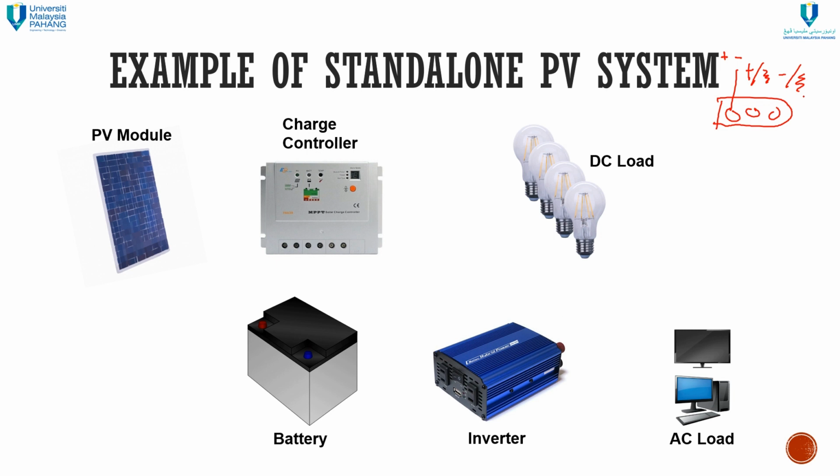So, let's connect all the things. Sorry, we don't have the hardware in front of us because we are online, but still the very basic of connection. Okay. Basically, we have the plus and minus from the PV module. So the plus one, we are going to connect with the plus one. Okay. So everything will be interconnected to the charge controller. Charge controller is just the controller that controls the output from the PV, the charging and discharging current inside and outside from the batteries. And the use of the load also is determined by the controller.